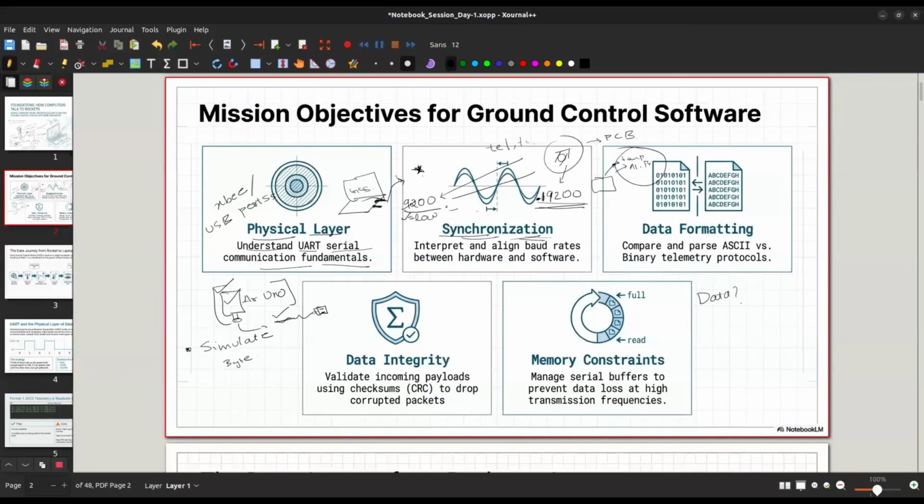You're going to design the ground control station so that it only receives these three values. You'll create a graph of temperature, a graph of altitude, and a graph of pressure, and you'll give out values saying temperature is equal to this much, altitude is equal to this much, and pressure is equal to this much. And this, my friends, is a ground control station that you have built.